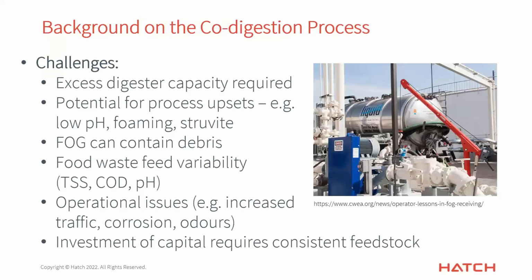One of the background materials that I was reading in preparation for this webinar, where I got this photograph from, had a really excellent explanation of how one particular facility in California was really challenged by the fact that they were set up to receive all of this FOG, but when it arrived, it had a lot of grit and stones and other things in it that made their life really difficult, and it really wore out their equipment very quickly. So that is a challenge there. If you were receiving pure grease with nothing in it, then probably you're all set to go. But otherwise, you have to do a little bit of pre-treatment on that FOG before you can put it in your digester.